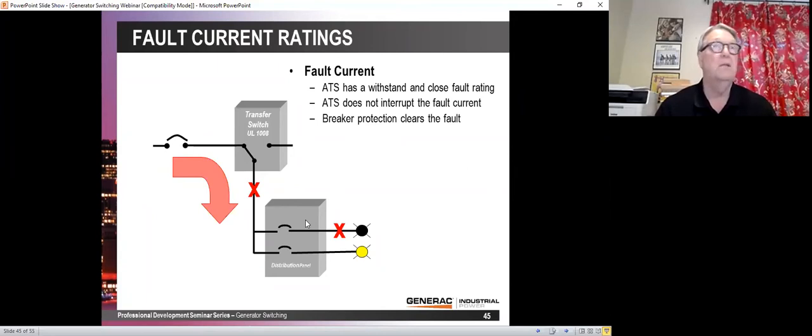And so they looked at the short circuit current of a transformer like that with some motor contribution and settled on 65 kA because that would let you use a 2500 kVA transformer. Prior to that, engineers were using no more than a 1500 kVA transformer. And so this was a great thing for system design.